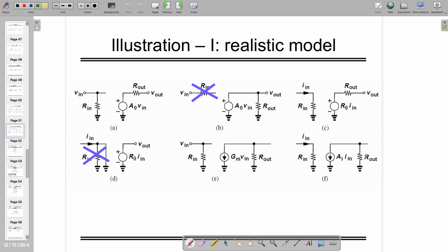So you need to make sure that you are connecting current with current, voltage with voltage, so that there is no problem in loading, or it will not create a problem. You cannot connect a voltage terminal directly to current or current to voltage and vice versa. For that, it's very important to know which kind of amplifier it is and where to connect that one. Or sometimes it has to be converted from voltage to current or current to voltage, just to make sure that you are connecting the right quantity when you are keeping it in the negative feedback loop.